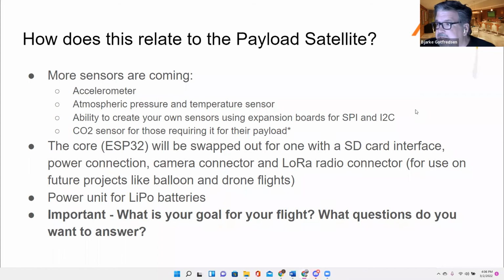This 10-pin connector here supports I2C and a serial connection. There's a couple of pins for programming the master, and then there's one pin we have allocated as a GPIO pin that's currently being used for the soil moisture sensor. So that's the different pins you will have on this board here. There's no SPI, but there is serial and there's I2C.